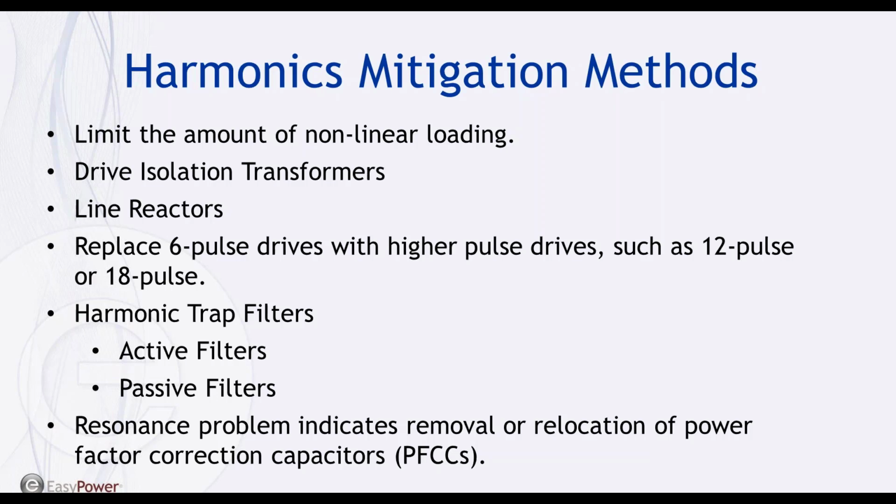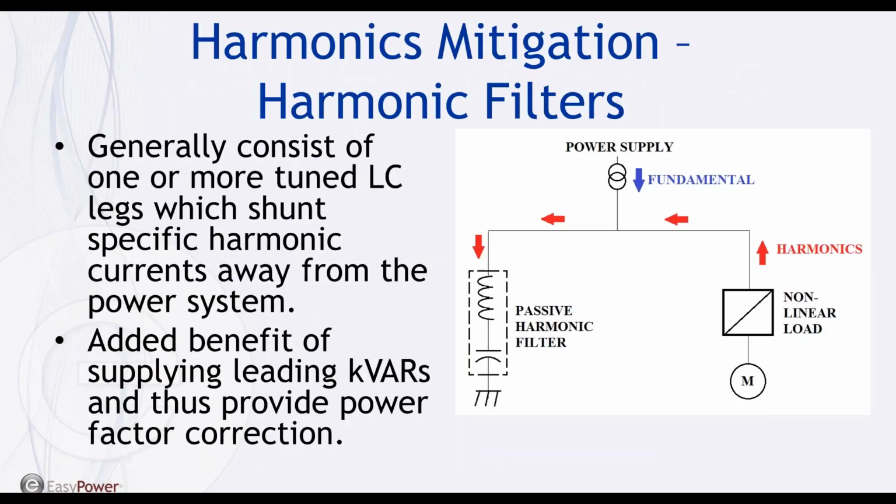Overall, it's important to understand how the various system components interact with each other and with the power system. It is essential that a coordinated solution be provided which meets total harmonic distortion levels, system performance demands, and power system requirements. Correcting harmonic distortion problems in the field after installation can be very challenging, time-consuming, and very costly. So now I'll go over a few of the different filter types available for harmonics mitigation.